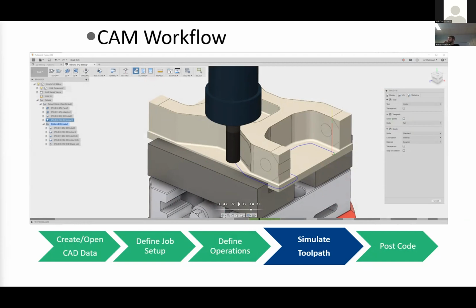Yep. All machines run on the same code. So there are different post processors for different machines. Some machines have different controllers and their own proprietary commands. One machine might have a different command to turn on coolant or to spin up the spindle. And so we have what we call a different post processor. Fusion has a library of these post processors, and they just translate the same computer code to the different machine codes. Usually if you're on a machine, that'll be provided to you or your company will have it. The Bechtel Center has their own. So sweet. Any other questions?